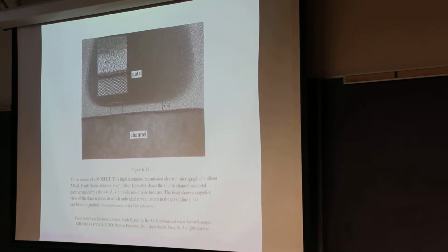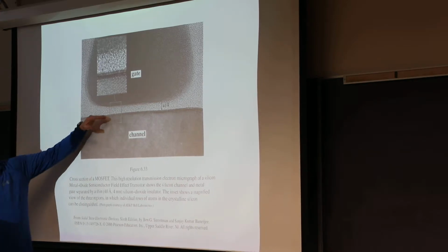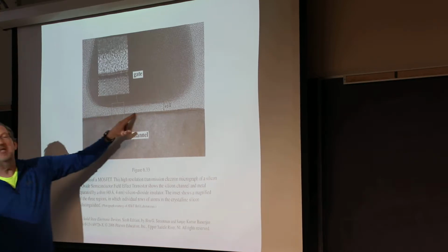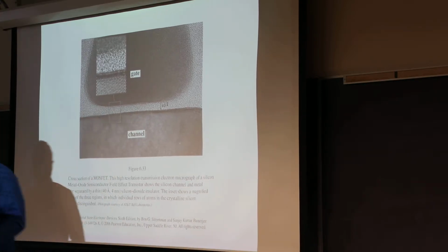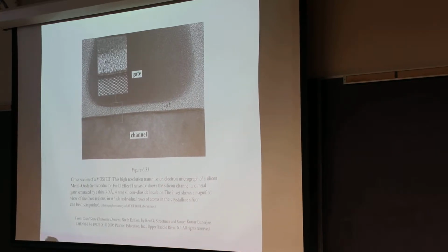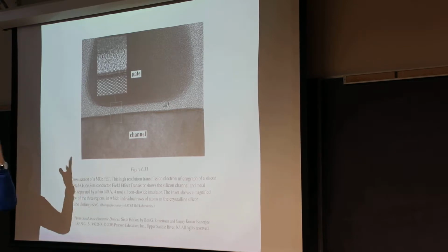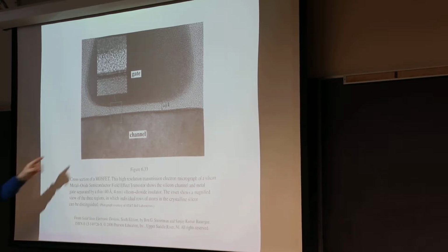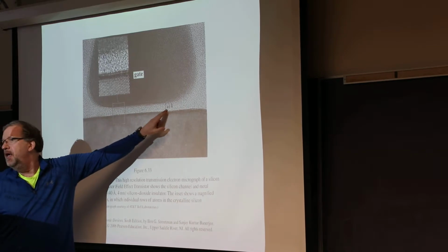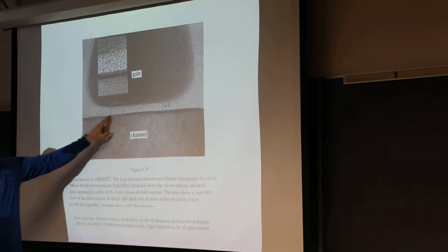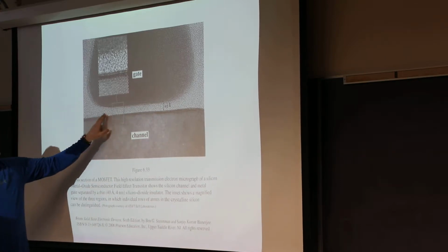Ah, yes, it's virgin silicon, right? Remember, because it's oxidized from the outside in, this has never been exposed to contamination. I don't care how clean your clean room is, there's always going to be some sodium vapor, something in the air, aerosol, something. Maybe you can get rid of the particulates, but you're not going to get rid of every contaminant. And therefore, this is really clean. We'll get into that more deeply when we get into the transistors, but I wanted you to understand the material science behind this.